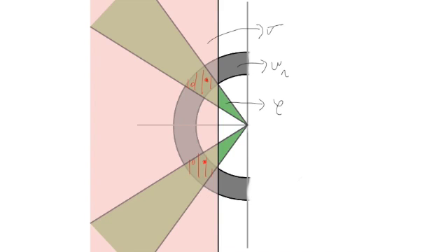So we get the maximum oscillation in this system from the point at the top. For this point here, we get the maximum oscillation. Actually the distance between the real axis and the pole location is giving us the damped oscillation. So we can find the value K here that will correspond to the maximum oscillation.